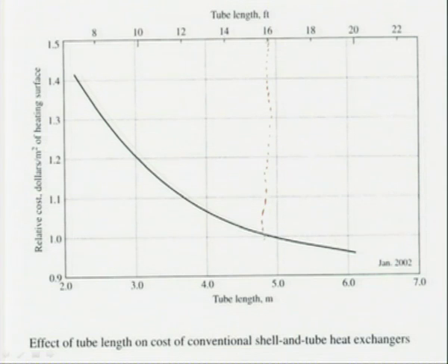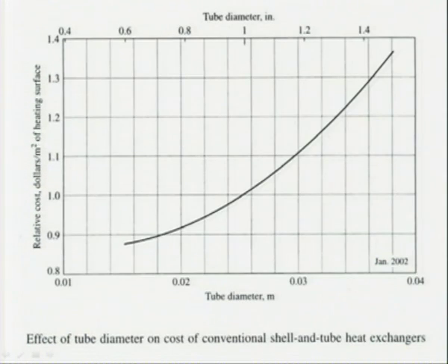Here we get approximately 1 and here 0.97 for 20 feet. Here 0.9 and 1, in between we can say this is 0.97, this is 1. So, that is the ratio of correction factors for the tube length. Thereafter, we also have to go for the ratio of the diameters. Now, our diameter is 2 inch. This particular correlation is only up to 1.4 inch, so we have to extrapolate this.